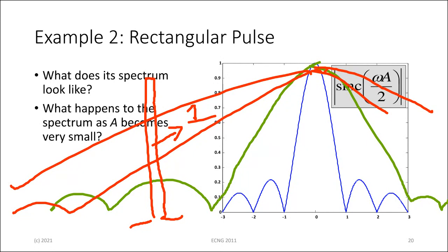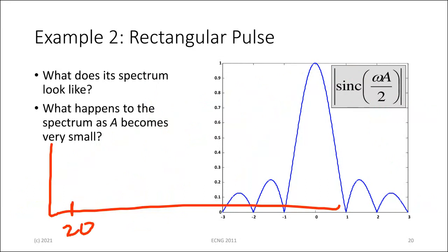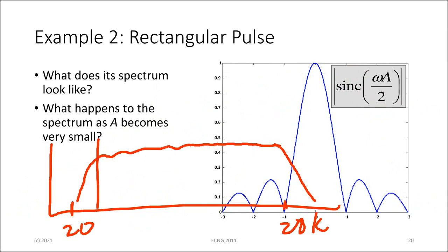When you make a loudspeaker, you want it to perform over that audio frequency range. If you measure the frequency response for the loudspeaker, let's say this is 20 hertz and this is 20 kilohertz, you want it as flat as possible over as wide a bandwidth as possible, right? The better the speakers, the lower the frequency, and over the human audio range, you try to get it to remain as flat as possible.